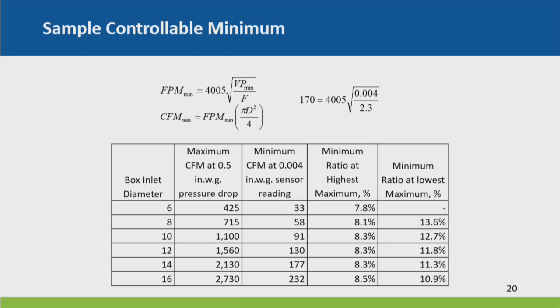It sort of depends on how you size the box. But we did another research project where we found that sizing it for 0.5-inch total pressure drop was life cycle cost optimum. So starting with that, we can end up where the minimums are between 8 and 12%. So it's way lower than what everybody else thought over the years.